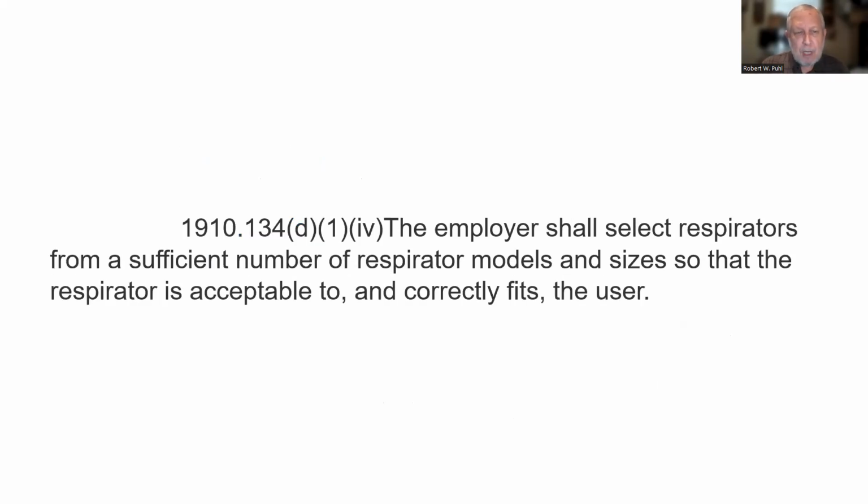The employer shall select respirators from a sufficient number of respirator models and sizes so that the respirator is acceptable to and correctly fits the users. Now, you don't want to get into respirators from a whole bunch of different manufacturers and stuff like that. You'll have a nightmare on your hands. You want to try to keep to one model, but different sizes. Because if you don't, it'll be a nightmare if this one's wearing this kind and needs these particular canisters. But if you're going to go into a respirator program, you might want to get with somebody in that field and get their input.